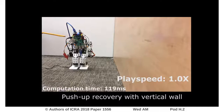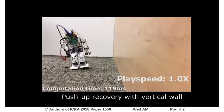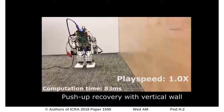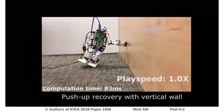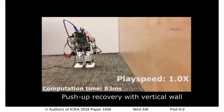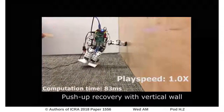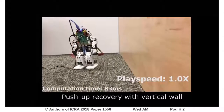A heuristic push-up recovery method is utilized in our experiment after the robot has already been stabilized. The robot will bend its elbow first and then stretch the elbow to generate a momentum in the direction away from the wall. These two examples demonstrate that the push-up recovery method can recover the robot to a standing posture and enable the robot to continue on its previous task interrupted by the push.